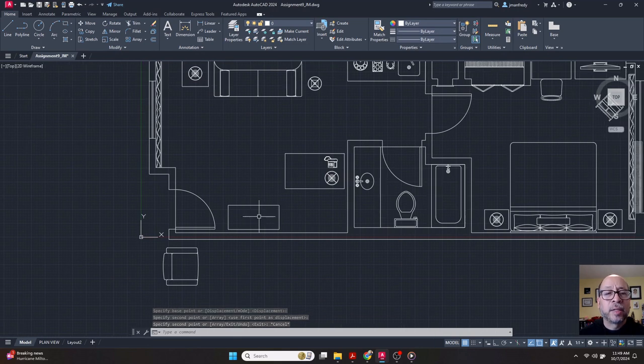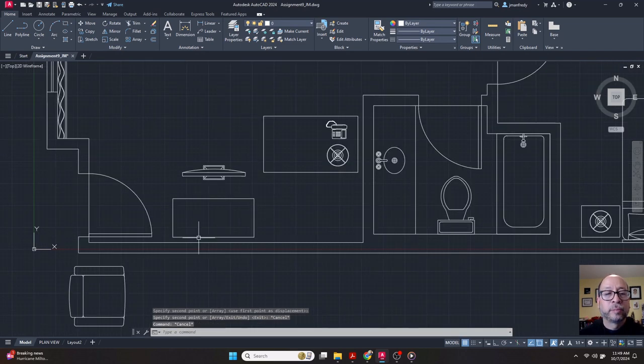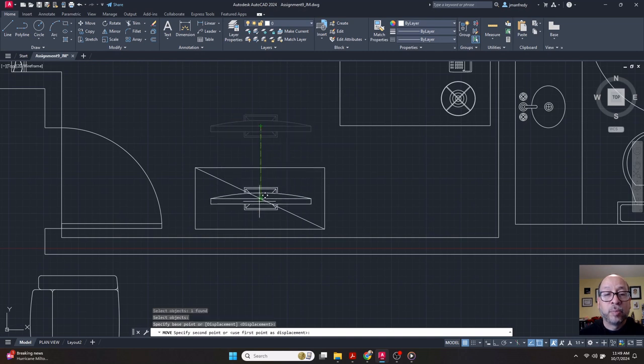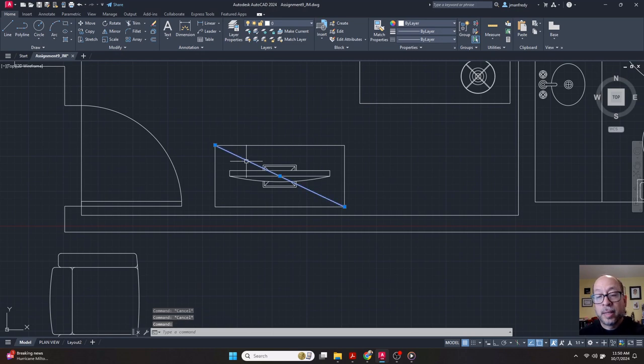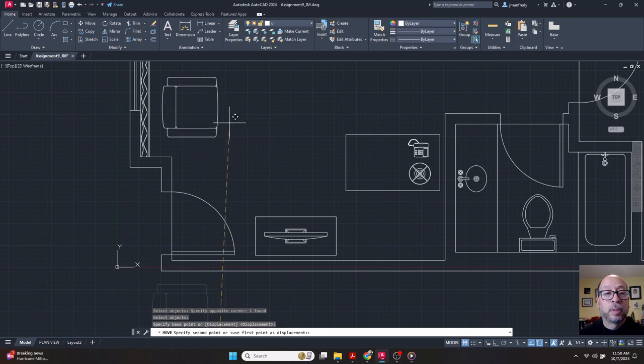There's a tape. There's a TV set here. There was one over there. I'm going to copy that TV set and move it into here. I will then locate it by way of this line here, and I will move it by selecting its midpoint to midpoint. Then I can rotate it using the midpoint again. It starts to rotate, and it's asking for the angle. I'll type 180 degrees to flip it over. Escape. I will erase that line there by delete. This chair gets placed near the curtain somewhere.